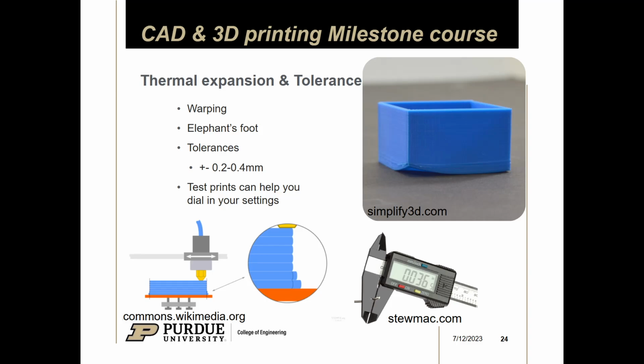So if you have a little bit of a chamfer, that extra squished out from the elephant foot can typically be a non-issue, if that makes sense. These are just small tips that I picked up over the years when printing stuff, but hopefully it's useful to you.